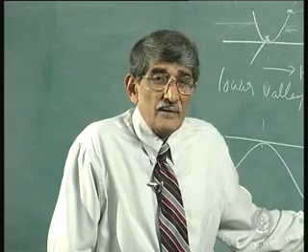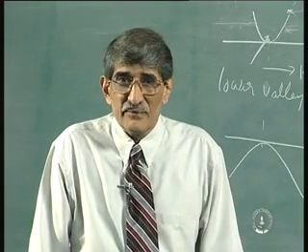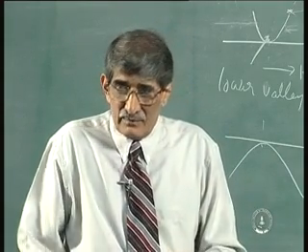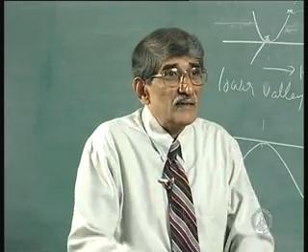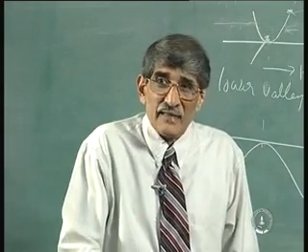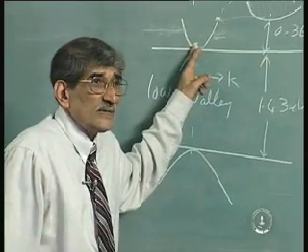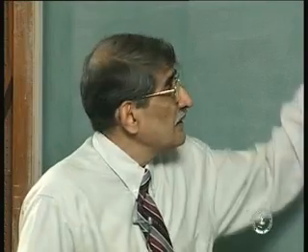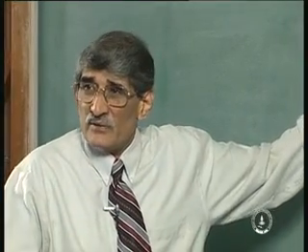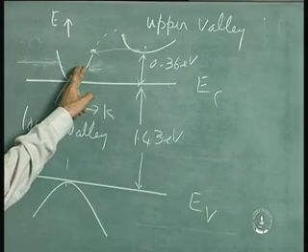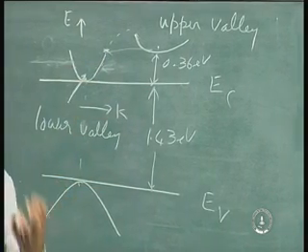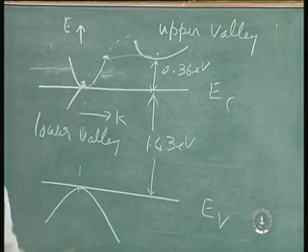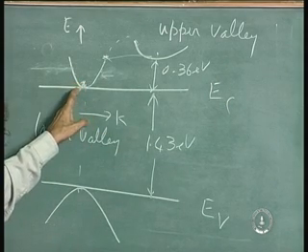The effective mass comes up because of that potential change due to the charge in the nucleus. In gallium arsenide, an additional field comes up. What is the additional field due to? Between the gallium and arsenic, there is a net charge difference. So, between the two atoms, there are additional forces coming up. Because of that, you have the effective mass smaller. That is the physical concept. In terms of the energy band diagram, this is sharper there. The effective mass itself comes up because of additional forces present between the atoms in the crystal. Here you have extra forces coming up because of the charge difference between the gallium and arsenic atoms. That is why effective mass is much smaller here compared to that of silicon.